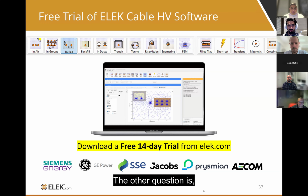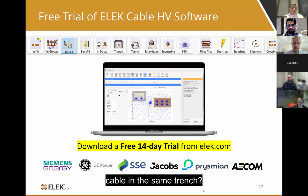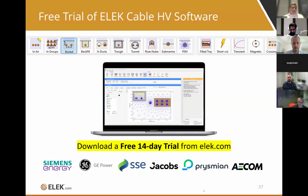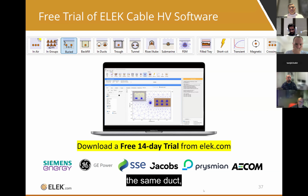The other question is, do we support hybrid systems, AC and DC cable in the same trench? Yes, we do. You can have AC and DC cables together. If you use FEM, you can even have them in the same duct. But in the other IEC methods, we can support hybrid systems for direct buried or in ducts.